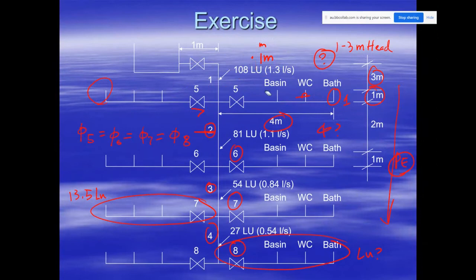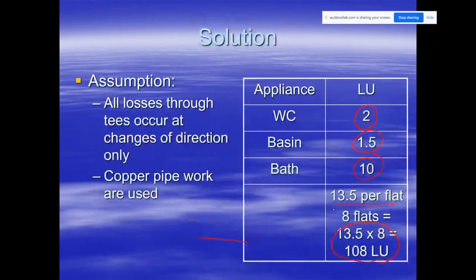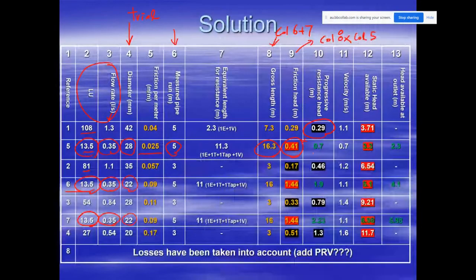Now, I make it simple, okay? Because I consider this path. So we did something for this part, and then the second part, I calculate for this. So this one, the pipe section number 1, pipe number 5, this is the progressive frictional loss. Okay, so this is 0.7.